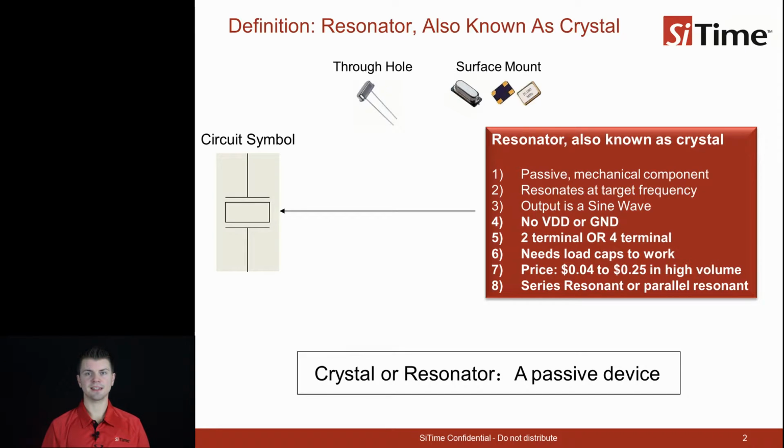A crystal resonator is a passive device with no power or ground terminals. It is used as the high Q element in an oscillator circuit. A complete timing circuit usually consists of a crystal and inverting amplifier plus two capacitors for the most commonly used Pierce oscillator and parallel resonant crystals. The capacitors and crystal resonator are discrete components placed near the IC containing the inverting amplifier.